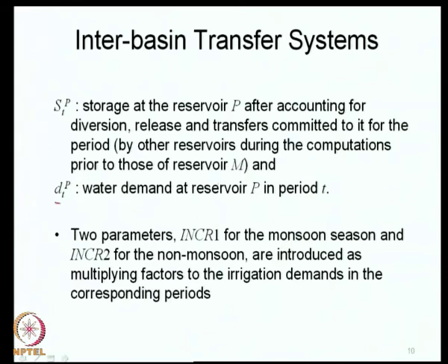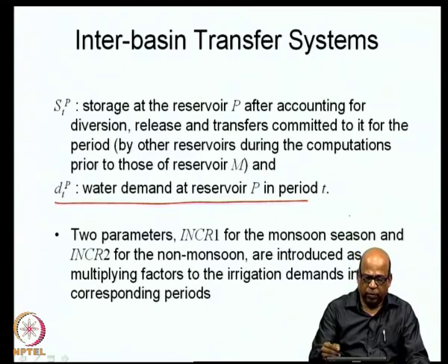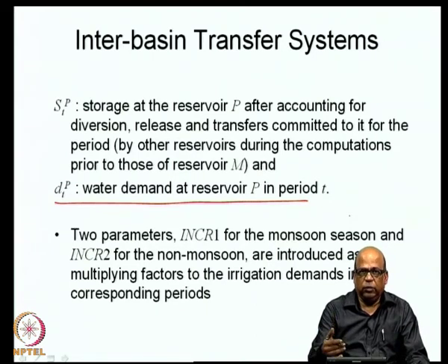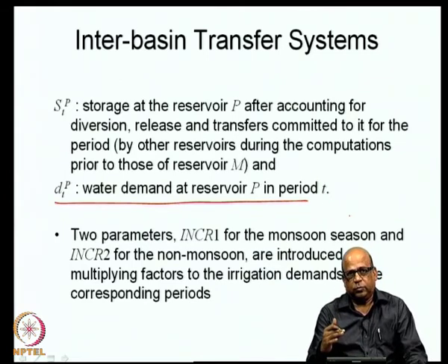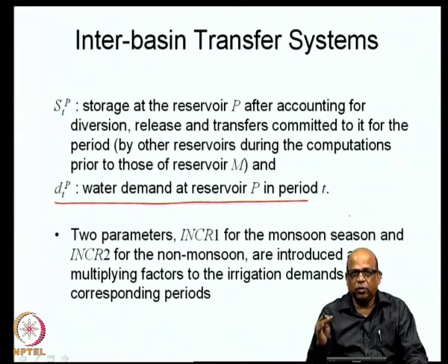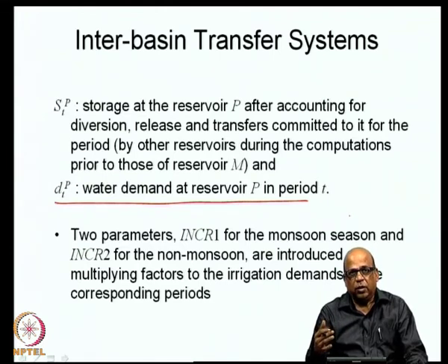when you are able to meet the water demand at each of the reservoirs by accounting for releases, by accounting for storages and so on. When you do this, if you see that all the demands are met, all the existing demands are met, then you start looking at, can we increase the demands? What I mean by that is, can we increase the irrigation potential? Can we increase the hydropower potential? Can we increase the municipal and industrial supply potential?